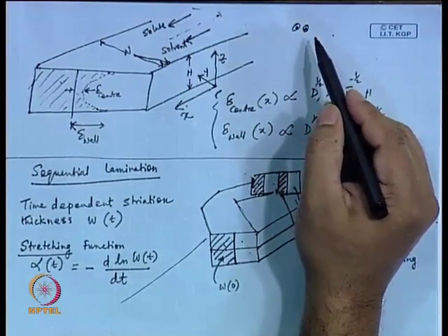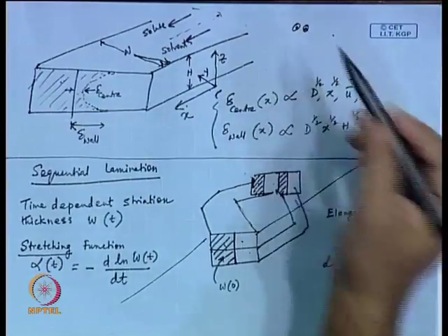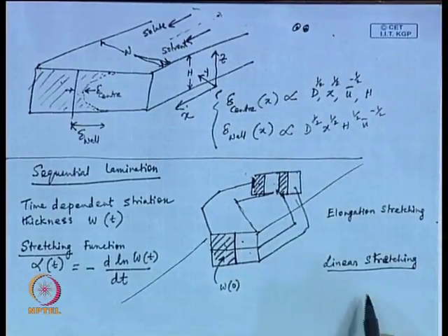Now, linear stretching is the stretching that we encounter in a viscous flow. One layer sliding against the other is also stretching, because one point near the wall and another point next door, because of this velocity gradient, are moving at different velocities.